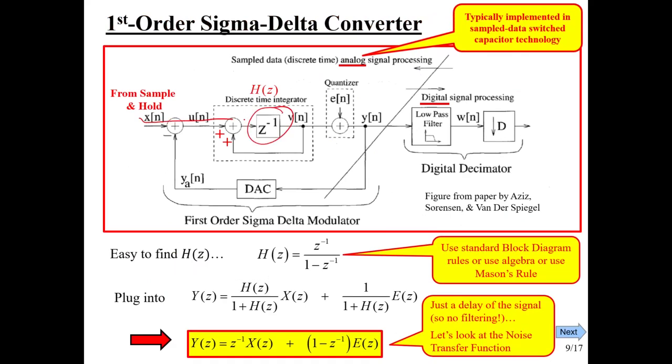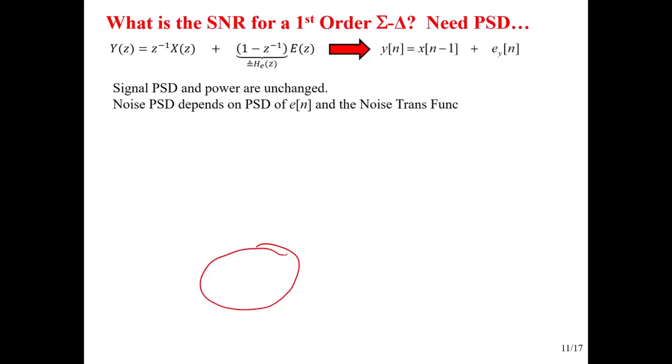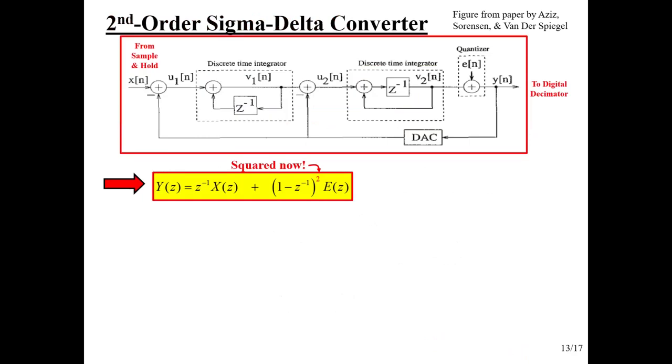That avoided the delay-free loop. Now I'll look over here. This one has it in the feedback. No delay going through there, but oh, thank goodness we have a delay in the loop. So we avoid the delay-free loop. That's why we do it that way.